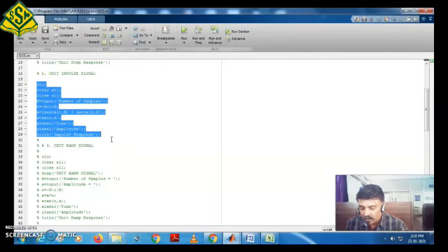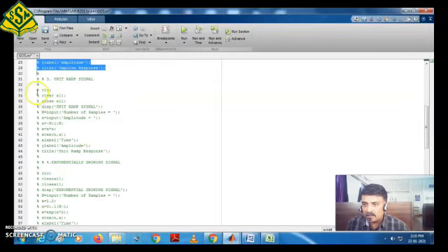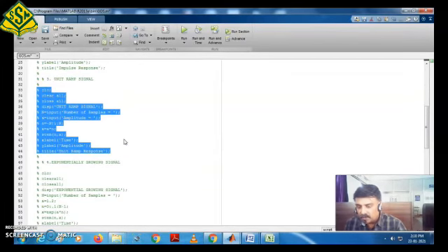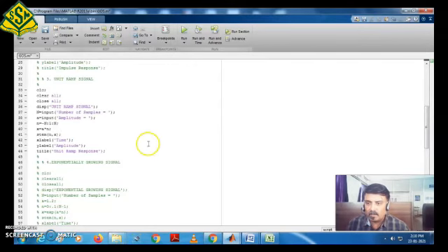Here I'm going to hide this and release the third program by using the key Control T. Control T is for releasing, Control R is for locking. So, unit ramp signal. You know the theory and syntax behind the unit ramp signal. Same story, with one additional line, display, just displaying the unit ramp signal. Whatever you write in single quotes, it will display in the command window.